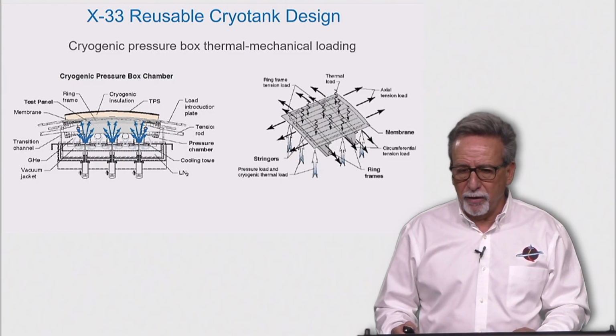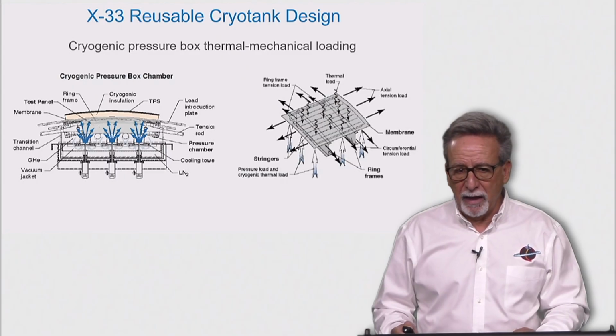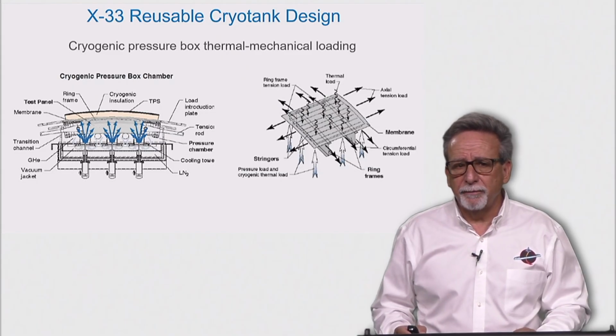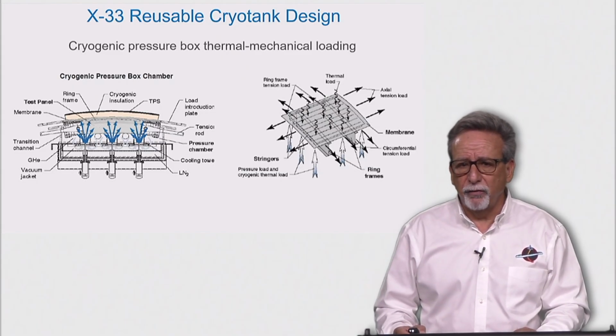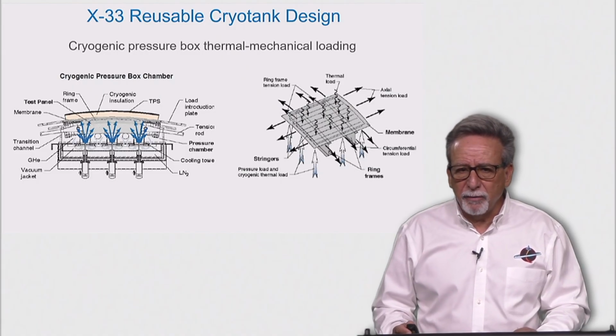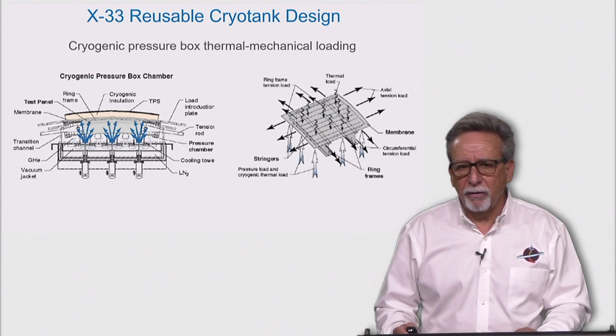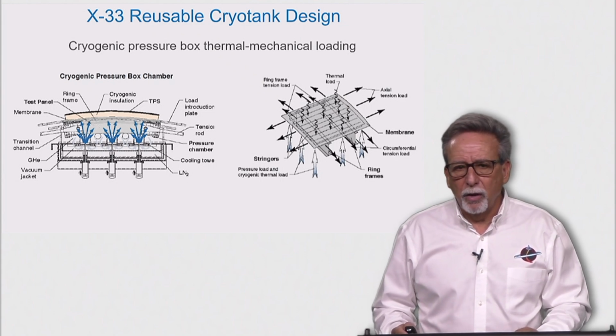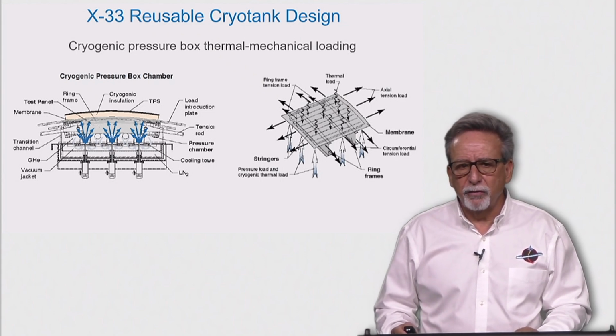In addition, both cryogenic and elevated internal temperatures and an elevated external temperature can be applied. The biaxial tension load is introduced into the panel by internal pressure, which is reacted through the load frame and by axial actuators. The maximum load applied to the actuators, not shown in the figure, is 2,000 kilonewtons or 450 kips. Circumferential or hoop loads due to pressurization are induced by the reaction force from the load frame through load introduction plates.